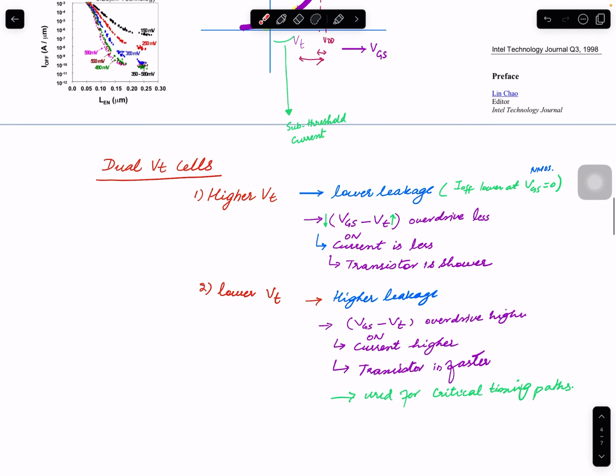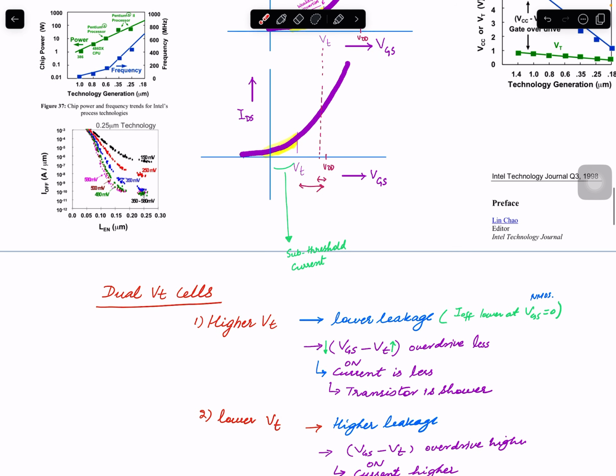The typical thing that people in physical design do, and have been doing for several generations of process scaling, is that we use a mix of different cells with different threshold voltages. So typically we have higher threshold, or higher VT, and lower VT cells like AND gate, NAND gate, and so on, in the standard cell library. There is a high VT standard cell library and there is a lower VT standard cell library. So somebody can ask you, okay, what's the difference between the two? So higher VT, and now based on this description, hope you understand that.